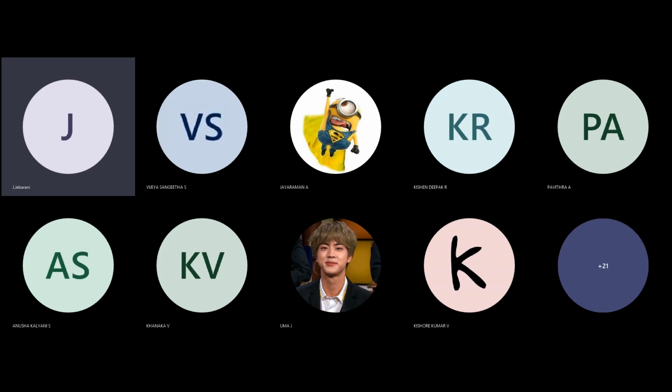So the upper layer and lower layer, or in other words the skin layer, is in a different color, and the middle layer is in a different color. It is successively injected through a common sprue out of separate injection units. So these are all the different processes by which we can make multicolor products with the multicolor injection molding process.